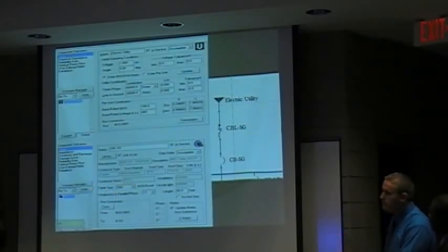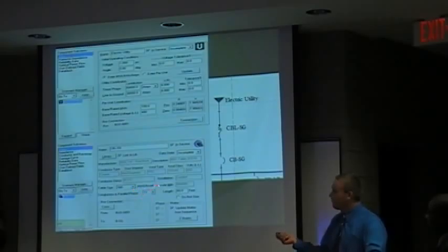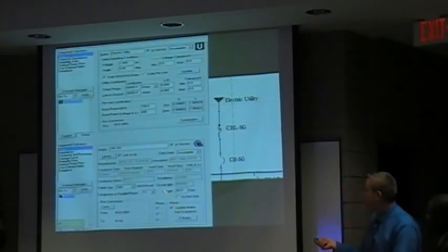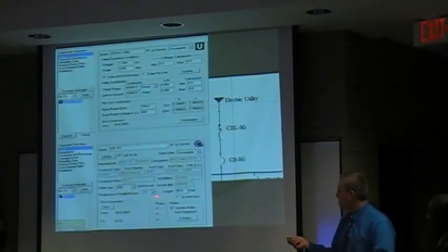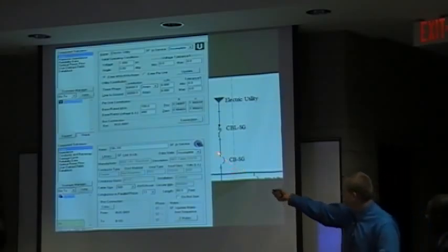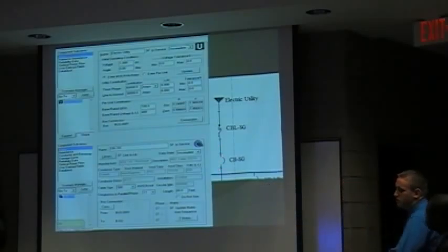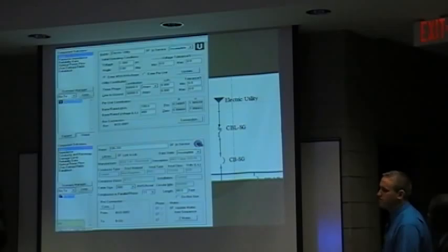And then based on NEC 310.15(B)(16), we sized our 4,000 amp circuit breaker to be 11 sets of 500 KCM, and we're running that at 60 feet. And then just below it here is our circuit breaker. That is a 4,000 amp Magnum DS draw-out circuit breaker.